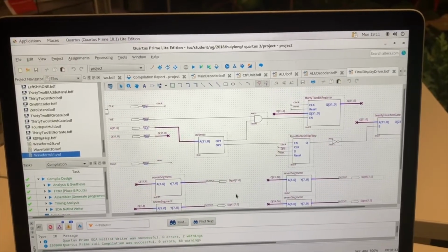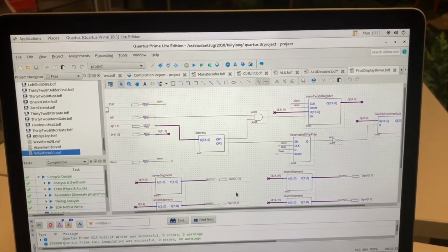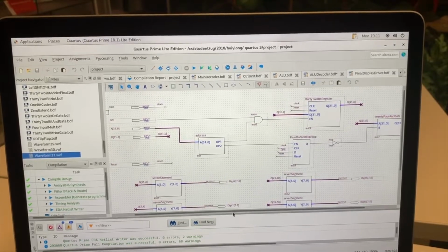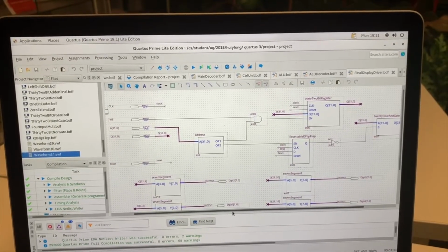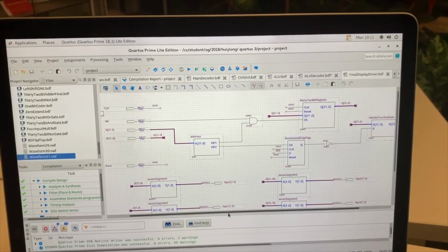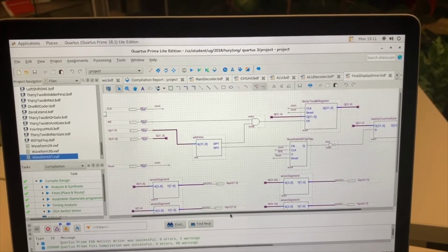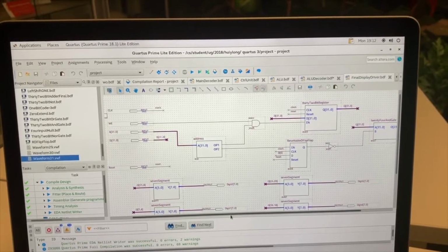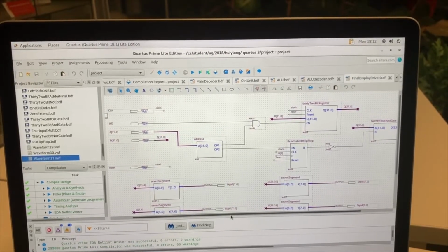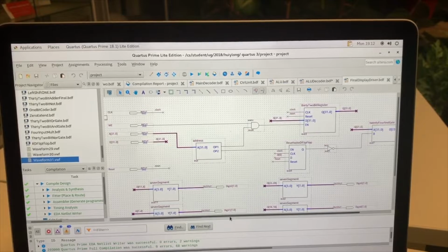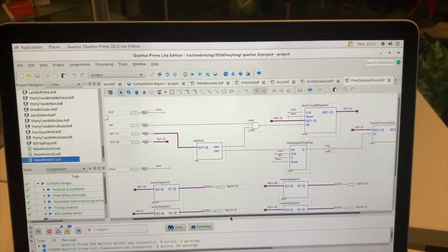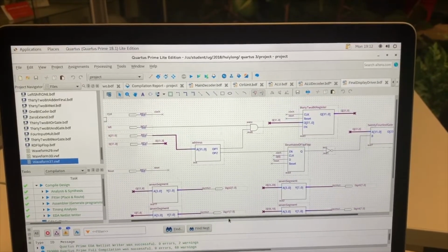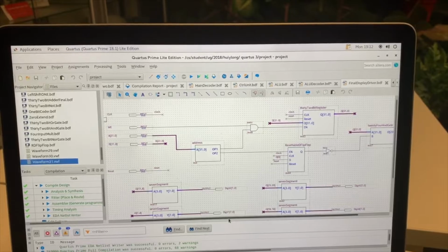For example, when the address is FFF0 and there is a rising edge on the clock, our FPGA shows the value stored in the register. When the address is FFF1 and there is a rising edge on the clock, 0 is stored and the display is switched off. Also, we turned off the decimal points by using 8 bits instead of 7 bits as done in Lab 4 earlier.